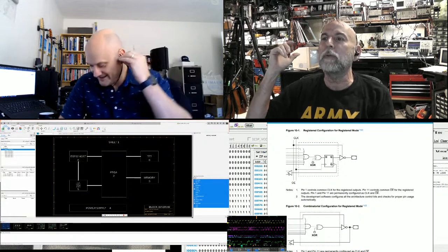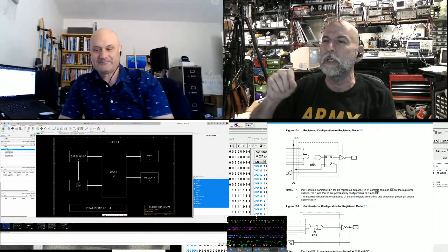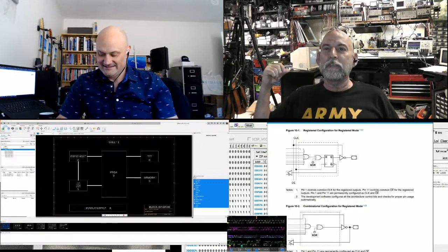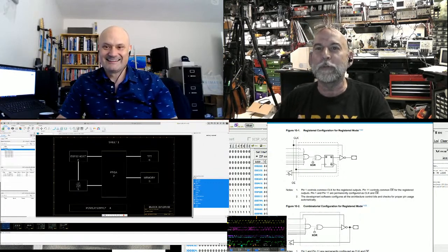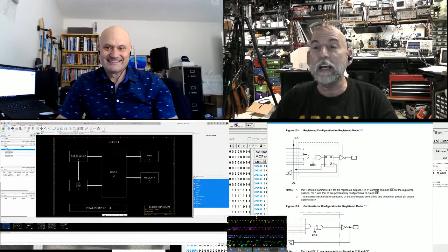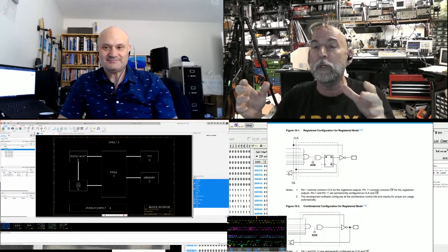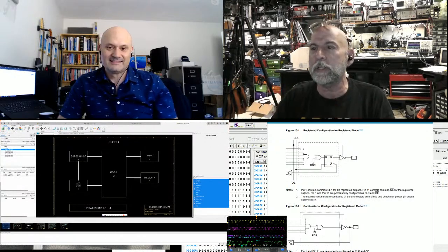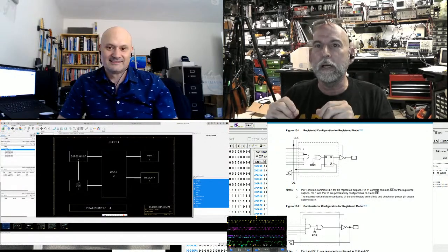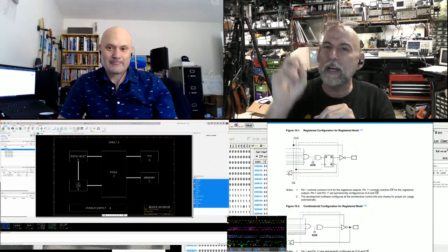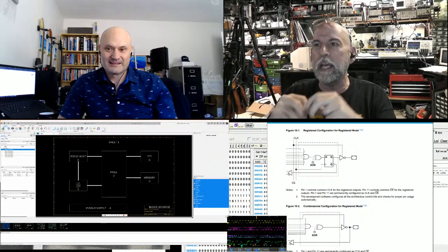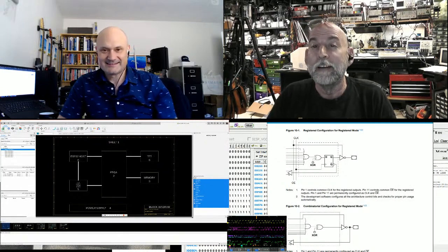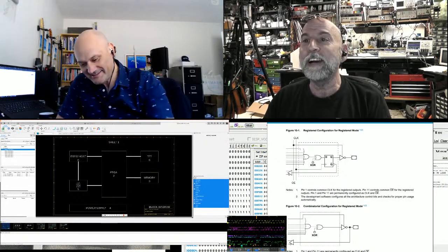The people that were doing the mini asked me a question about how the real hardware works. So for the second time in 35 years, I hooked scopes to a 128. And like I said, I combined analog and digital probes to create an address decode along with the clocks and the chip selects, and was able to go into a menu and say, this one's high, that one's low, this one here, and add them all together to create my trigger event, which was cool. Very cool. So, all right, we will see you